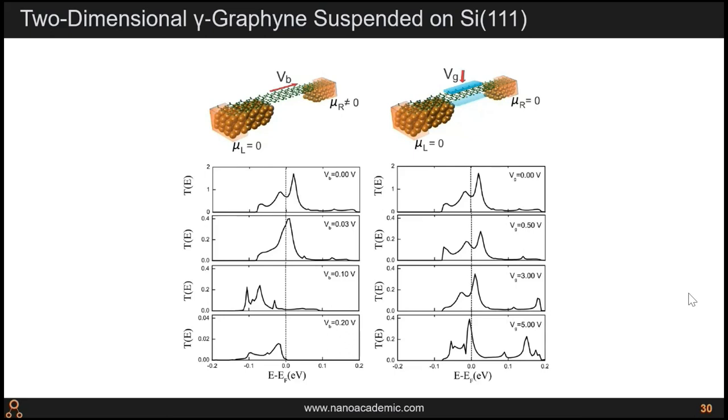And lastly, the authors looked at what happens if you put some bias voltage on these bridges or a gate. And basically, what is maybe peculiar compared to other devices, like semiconducting devices, is that here you can actually turn the device on and off by putting a bias voltage instead of just a gate voltage. So at basically low bias, this thing would be conducting, and the stronger the bias, the lower the transmission around the Fermi energy here.